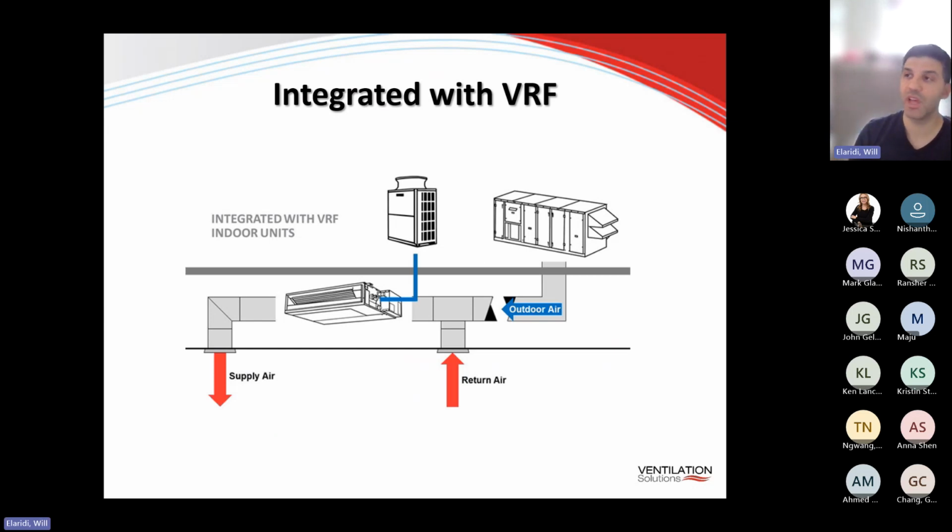It's really important to supply fresh tempered air, because if you bring in colder or hotter air, we don't want to oversize our VRF system, because that's going to increase the cost as well. If you bring in fresh tempered air, we're only doing minimal increases of heating or cooling. That way you don't have to upsize the VRF system. Typically a fan coil would allow 15 to 20% fresh air into the fan coil unit, while the rest of it would be return air. Since it's very well mixed, you're not going to get too much of a variance in entering air temperatures. But nonetheless, you are getting fresh air into each space in a more uniform way.